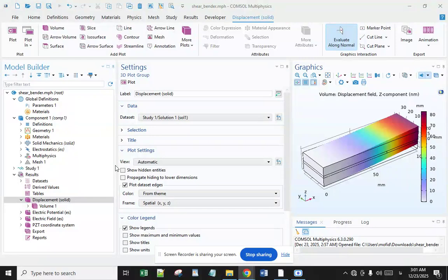However, a complex poling pattern results in the actuator due to the induced in-plane component of the electric field. This must be accounted for in any model. By sandwiching a piezoelectric layer between off-axis laminates, the composite laminate can produce twisting deformation to transform the piezoelectric constant e36 or d36, but this twisting is secondary since it is caused by the extension-twisting coupling.